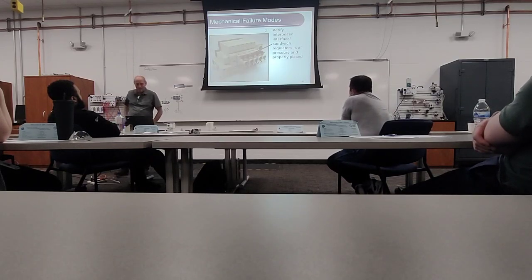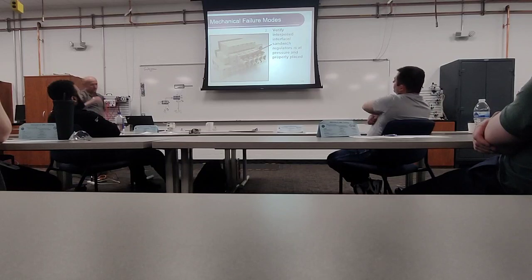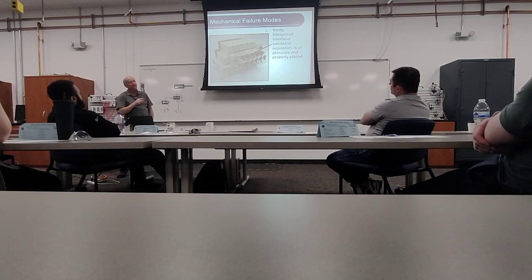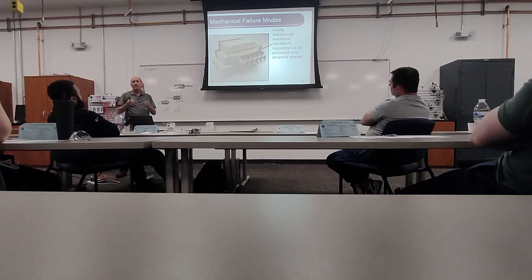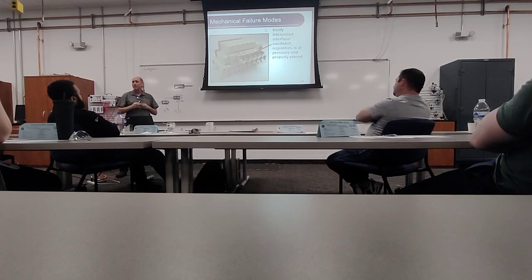We have valves on manifolds. Valves on manifolds can have layers to them. So there's different things we can put in. We can put regulators in here. So again, I've got 80 PSI in the valve manifold, but I've got a gripper out there. And I actually did this on the FMS. I've got one of my vacuums, and I actually put a regulator in between the valve so that I can drop the pressure down from the overall pressure I'm putting on the system. So it allows you to put individual pressures on individual valves.